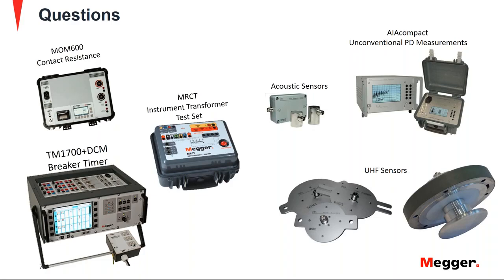But I would say, we are discussing GIS testing today, and as you saw during the presentation, you really have to analyze your connections, make sure that everything is safe and that you can perform each and every measurement. So typically for GIS, you seldom use the run all. So yes, you still have the capability to demagnetize, but you have to click the button yourself to demagnetize and do it individually. But yes, the unit does have the capability.